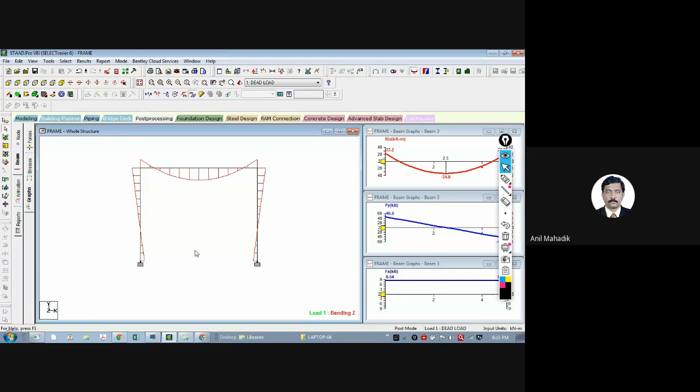If you have used ETABS, let me explain a little. See, in ETABS we can model the slabs. That is the first advantage, as a shell element. That means we can model the actual slab stiffness. In STAAD we cannot model the slabs effectively. What I'm saying is, we can model it, but it is very complicated, and I would say I don't use modeling of slabs in STAAD Pro because there are other issues regarding that. I will tell you ahead.